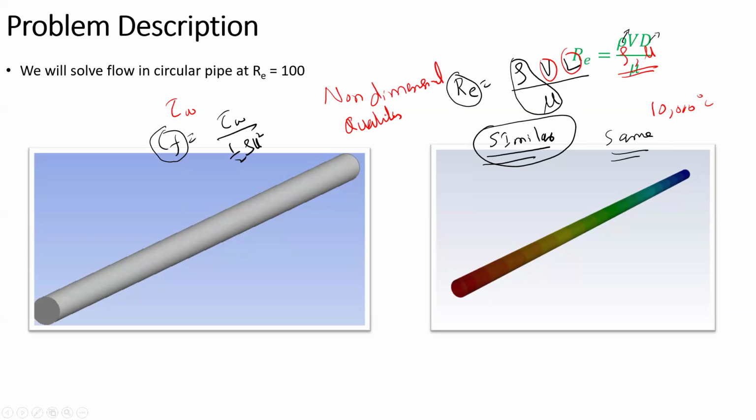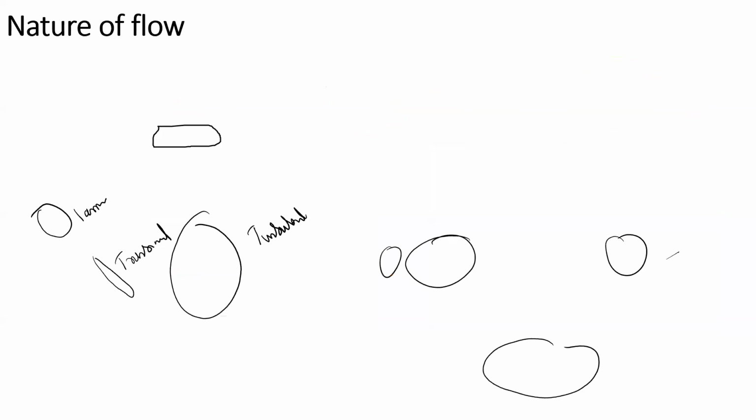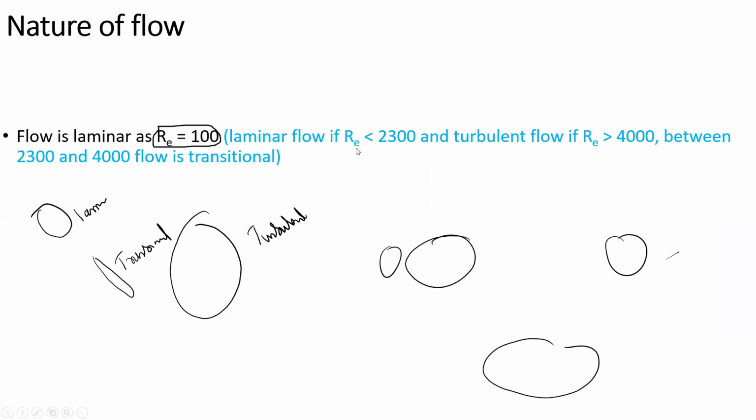So for example, in the wind turbine case, I have one wind turbine problem at a certain TSR, and this is the wind turbine type. Then I develop the geometry starting from the aerofoil coordinates, and then put them at the required radius, then consider the whole geometry, then domains and mesh, and then solution, and then compare the results with the available data.